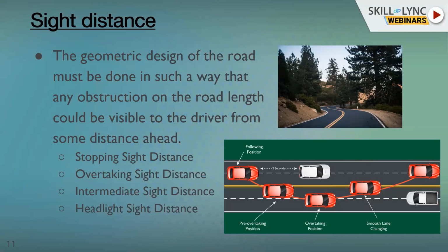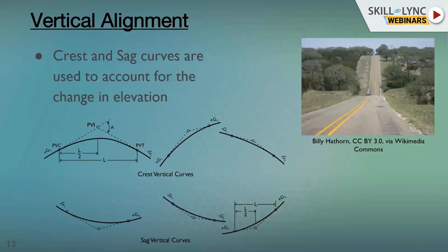What are the things that can affect our sight distance? Some issues will be the profile. In this location, if you see from the top, it is a straight line. But here, the vehicle you are not able to see because of the profile. So you have to raise your profile a bit so that you will not have this type of kink on the road. It is hazardous to the vehicles traveling on the road, right?